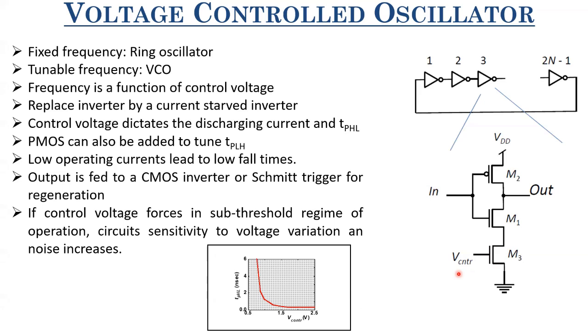So when you are biasing your circuits in subthreshold or designing subthreshold circuits, it's really important to ensure that mismatches are not significant, because otherwise it will lead to 10x change as compared to biasing in the saturation regime. So although in subthreshold you are consuming less bias current and gaining a lot in power dissipation, at the same time you're also losing robustness to noise, and you're also losing some of the speed. Okay.